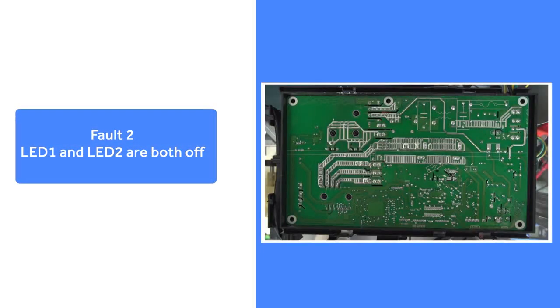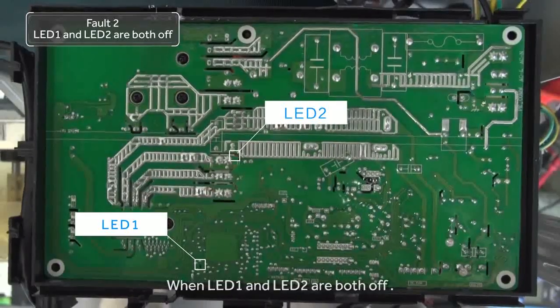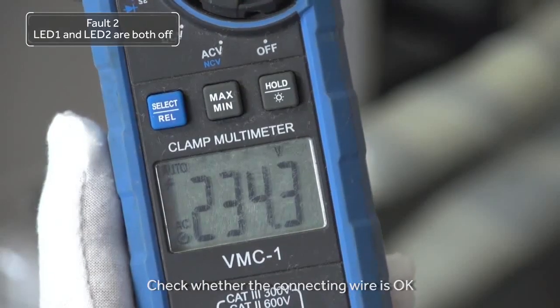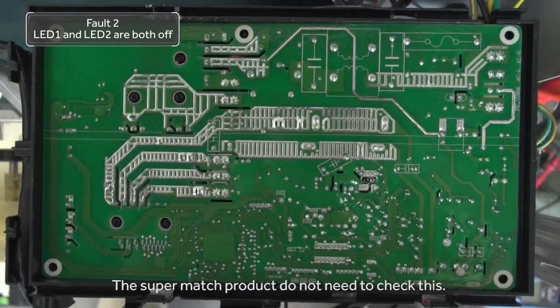Fault 2. LED 1 and LED 2 are both off. When LED 1 and LED 2 are both off, if there is no 220 volt on the outdoor terminal block, check whether the connecting wire is okay. The super match product does not need to check this.